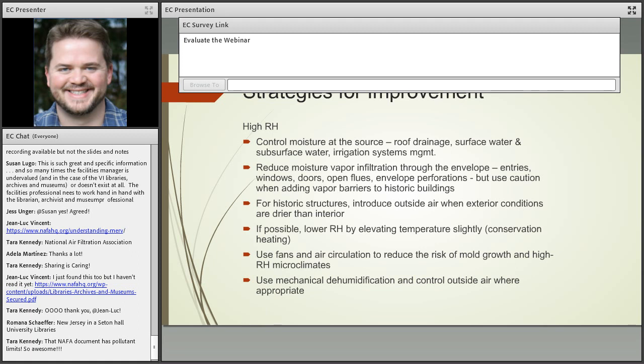Once that weather pattern changes, the likelihood is that you'll get some better performance and you'll be back, if you will, out of the woods in terms of thinking about your moisture control. So, also think carefully about whether or not it's the time to panic or when that time to really take action is. If you think that there is the risk of specific damage being done in the environment. But otherwise, materials do take some time to equilibrate to moisture content, at least most materials. So these short-term fluctuations may not always have the impact initially.